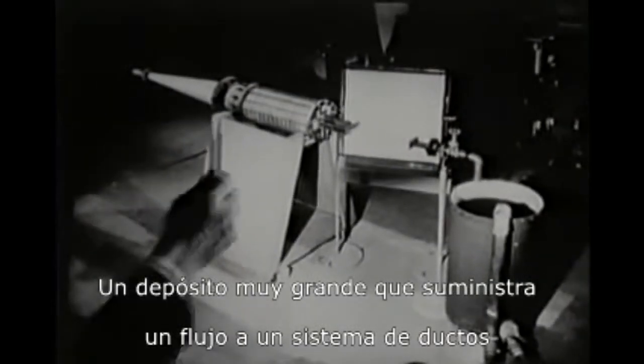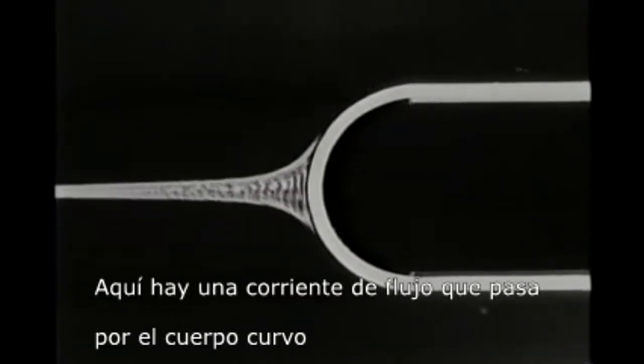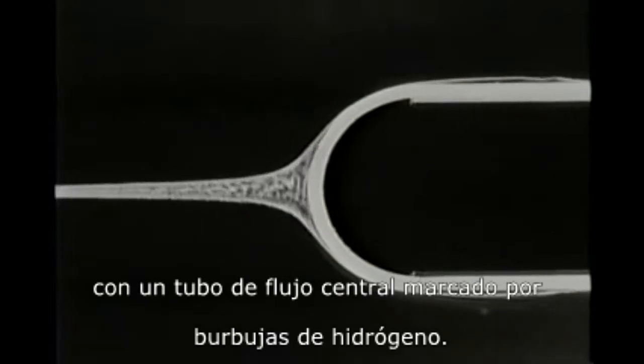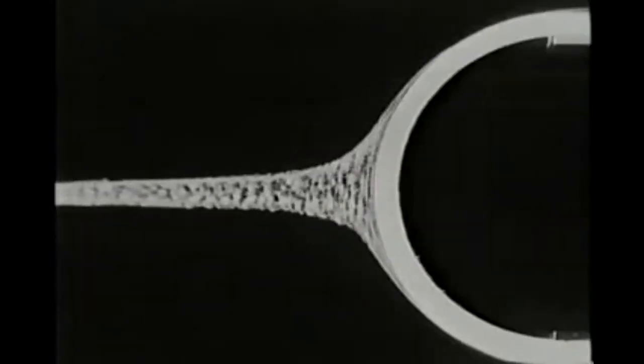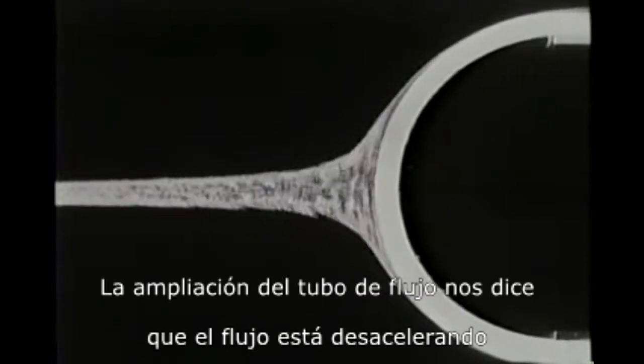A very large reservoir supplying a flow to a duct system is itself a stagnation region. Here is a streaming flow past the blunt body with a central stream tube marked by hydrogen bubbles. The widening of this stream tube tells us that the flow is decelerating. The singular point where the central streamline reaches the nose is a stagnation point. The speed is zero there.